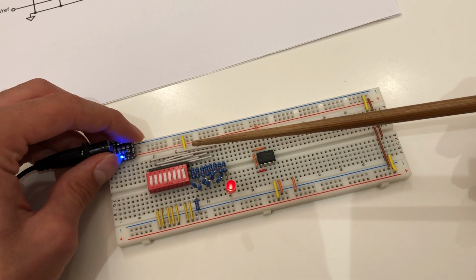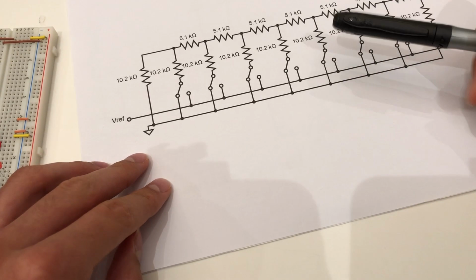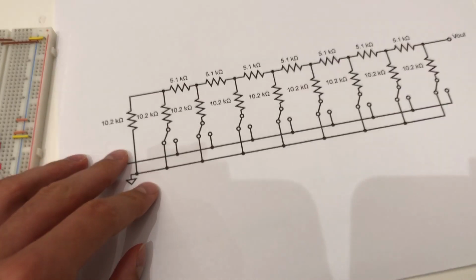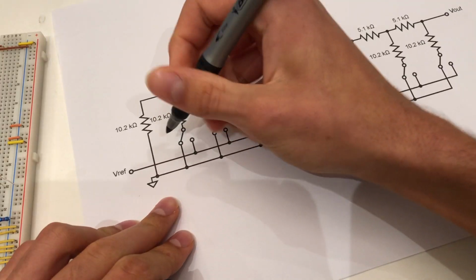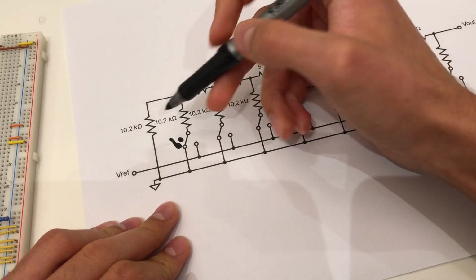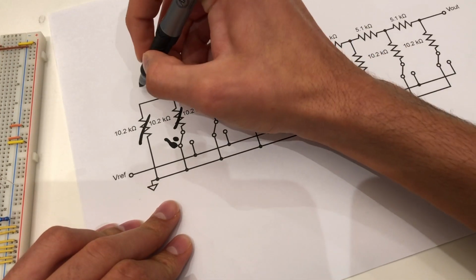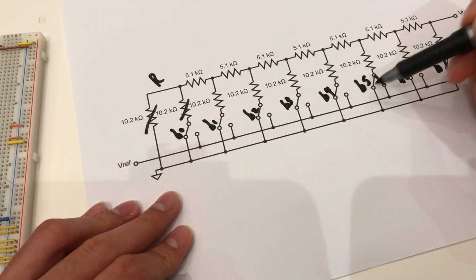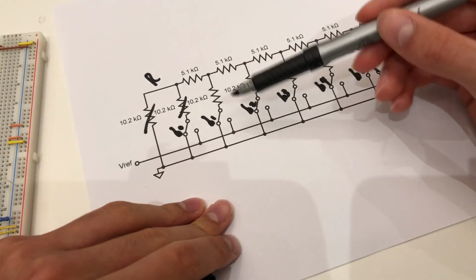Let's say you want to find the voltage value of a bit. Let's go with bit 5. To do that, we need to first simplify the circuit using Thevenin, then calculate the values with superposition. Above the least significant bit, bit 0, the two parallel 2Rs simplify to R. These two are simplified down to R. So we've shorted all voltage sources except for bit 5, and now we can simplify.